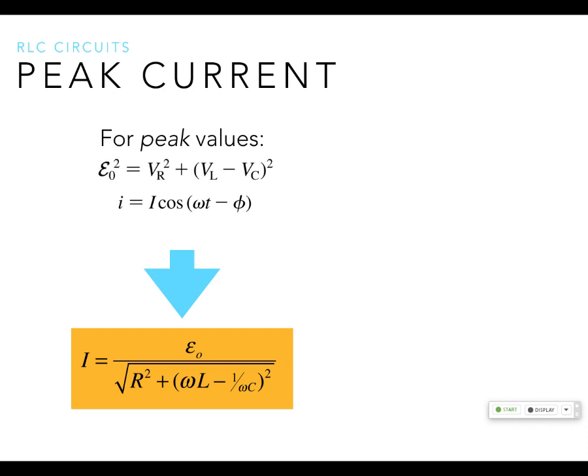This is still just V equals I times reactance. And remember, this is a series circuit, so you're just adding up the different reactances, essentially. Okay, but if you're adding up the reactances, it's not as simple as just adding them. You have to use this.